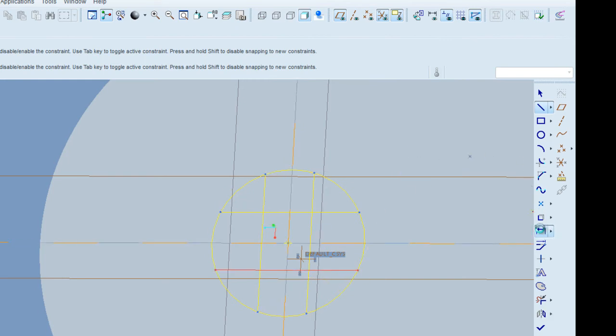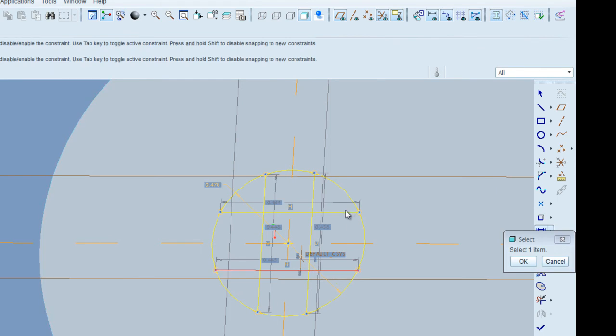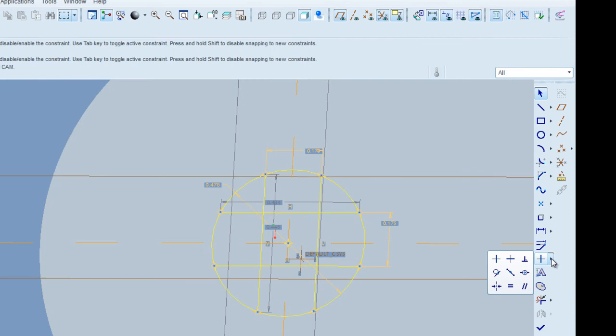What we want to do is, the width of one of the parts of the axle cross is 0.175 centimeters. It's also the same over here: 0.175, enter. And also centered with respect to the X and Y axes.